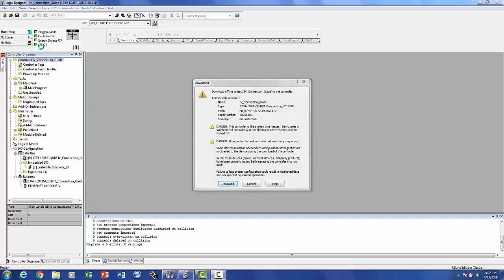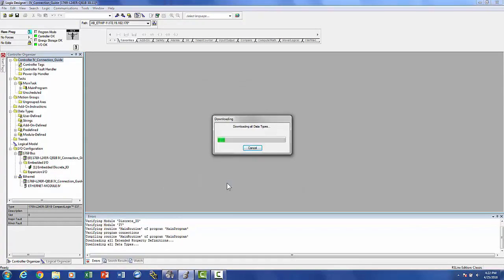If you do not have the tag file, make sure that you remember what type of module you created, whether it's DINT or INT, and reach out to your local Keyence sales rep or to Keyence tech support, and we can provide you with the appropriate tag file.